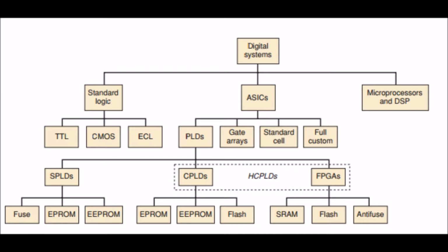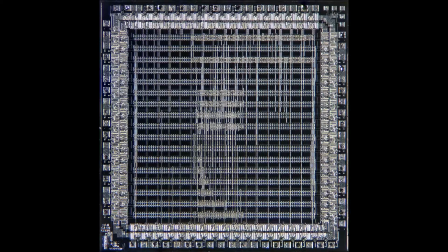Well, we're going to start with the ASIC, but what is an ASIC? An ASIC is an application-specific integrated circuit, and that means that it is customized for a particular use rather than intended for general purpose use. The maximum complexity possible in an ASIC has grown from 5,000 gates to over 100 million gates. That's a lot. And that means that modern ASICs often include entire microprocessors, memory blocks, including ROM, RAM, EEPROM, flash memory, and other large building blocks.